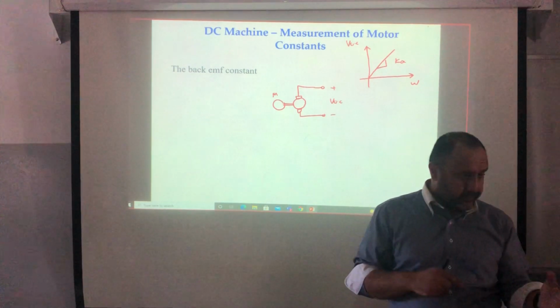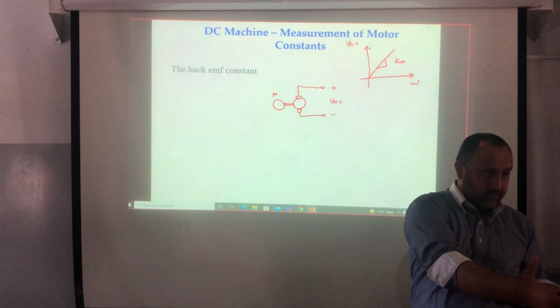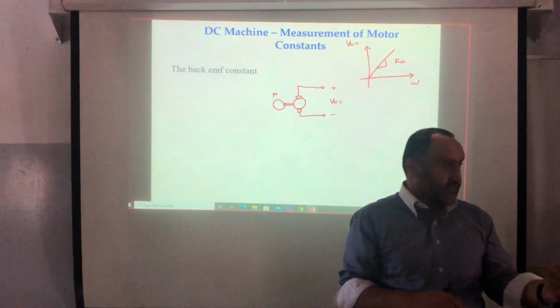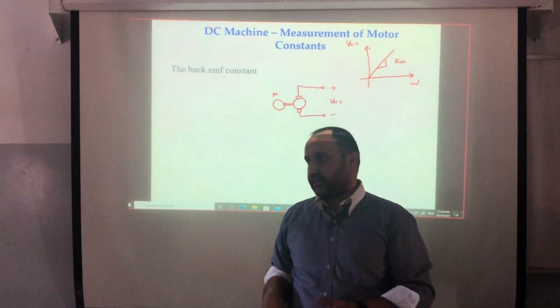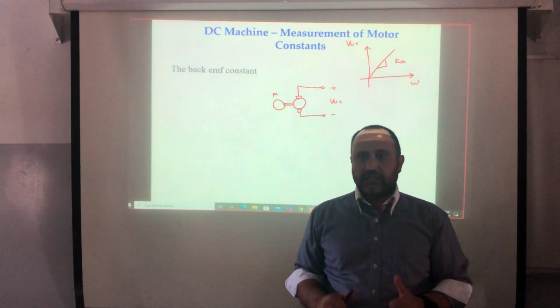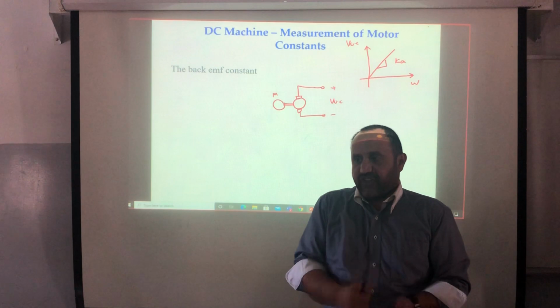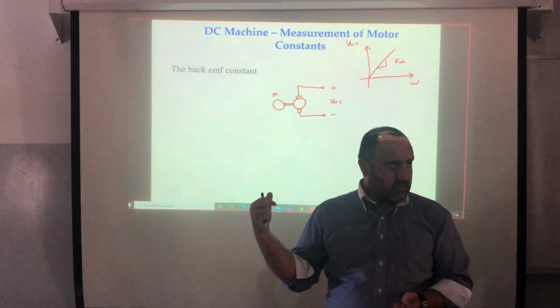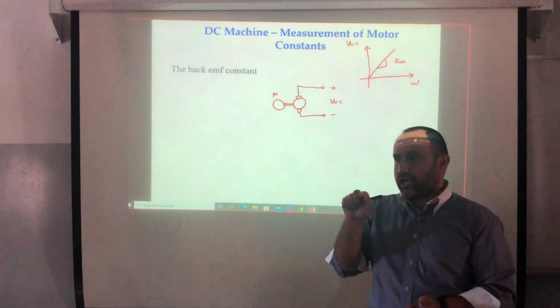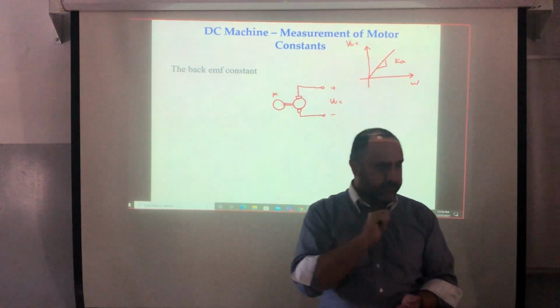So this means that the steady state error is equal to 0, if the system is stable, of course. So can I rely on that, which means that the current control is much faster than the mechanical part. So the current inside the machine is my reference.